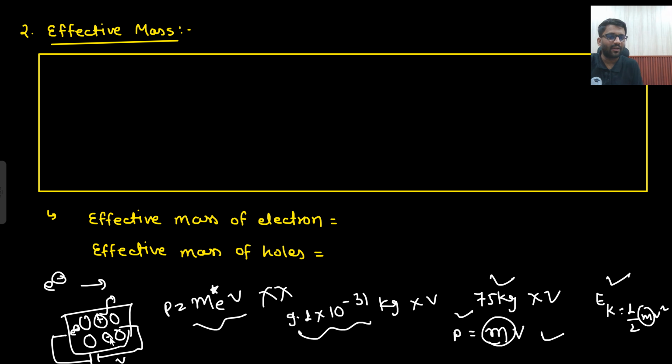If it is an acceptor impurity, then it will attract the electron. So here the movement and here the movement, both will be different, because here it is moving freely and in this silicon crystal there will be some hindrance as well, no? Like these atoms will be vibrating or there are impurities, the hindrance that I already explained, right? So this movement will be different and this movement will be different.